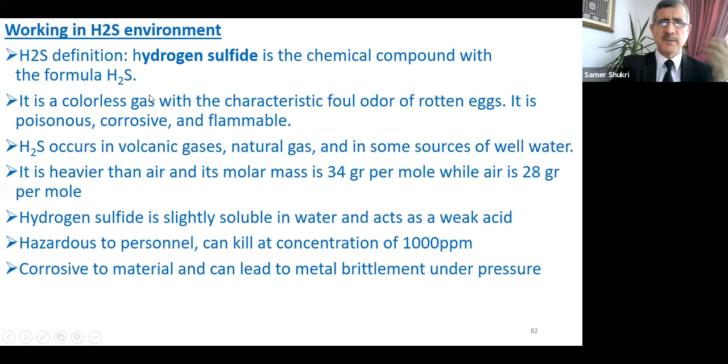It will be embrittled and will fail, and we will lose our equipment. So you have to familiarize yourself with the characteristics of H2S and know that it is corrosive. It has the odor of rotten eggs.